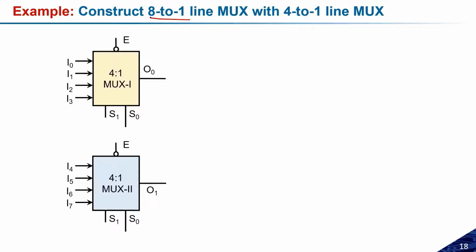But suppose I do not have a stock of 2:1 mux, then how can we solve that? I have a stock of logic gates, but I do not have 2:1 mux. Whatever you just responded is absolutely correct, and this is one of the possible solutions to design this structure. But if I don't want to use a 2:1 multiplexer, and I have to use only 4:1 mux and the logic gates, in that case how can it be done?